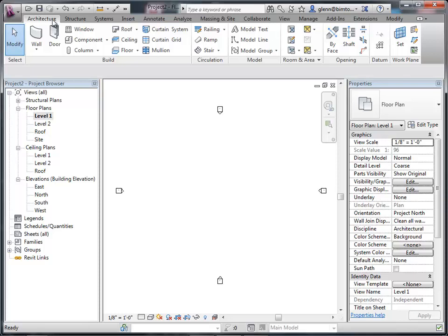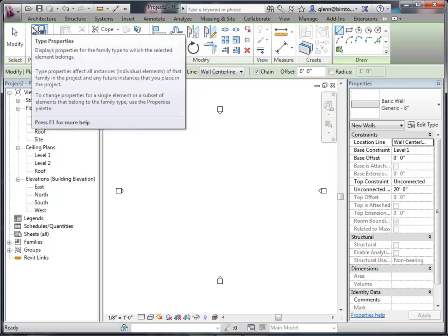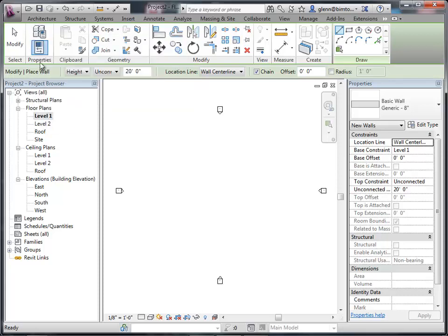So as you go through and, for example, choose the wall tool, let's take a look at what actually comes up. There are a number of different options that'll pop up that are going to help us really decide how to go through and place this wall. There are different drawing methods that are available over here. So we can place walls by drawing individual line segments.